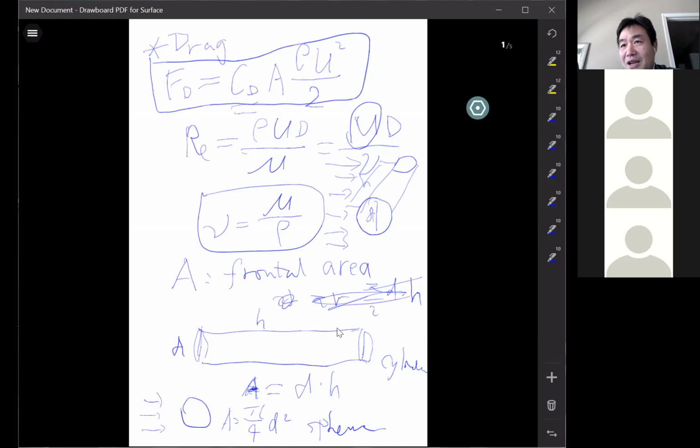Dimples on the ball actually create the onset of turbulence a little bit earlier. It's easy to create turbulence. For example, if you have a surface with some structure on it, not smooth, very rough, it's a very turbulent flow. So you create the onset of turbulence early, at a little bit lower Reynolds number, maybe like 10⁵. With that little bit of surface roughness on the golf ball, you feel the same effect as a higher Reynolds number. So suddenly you reach that gap, that jump.